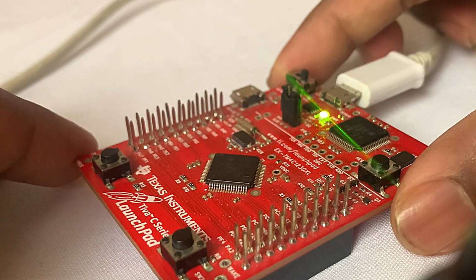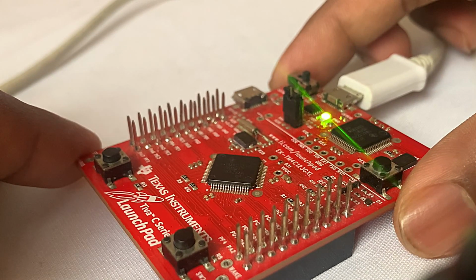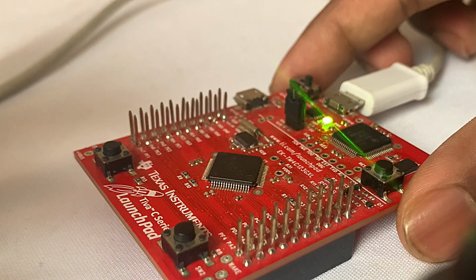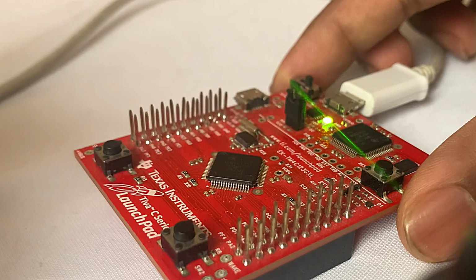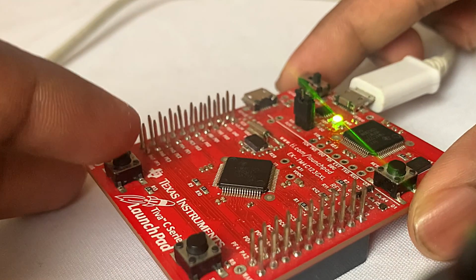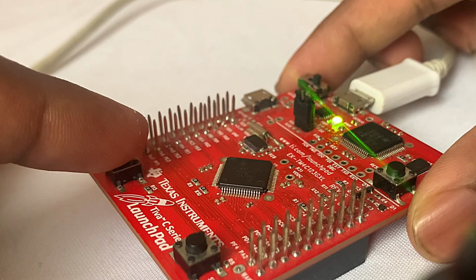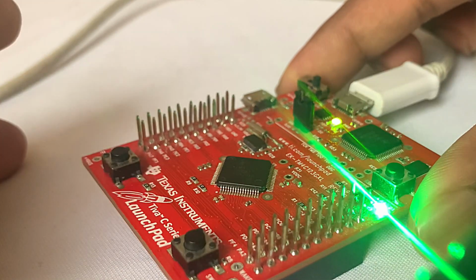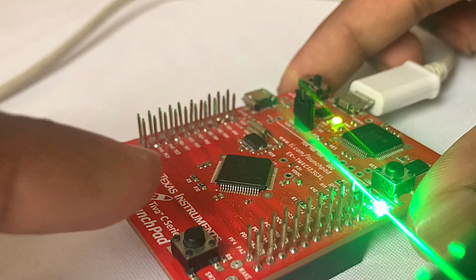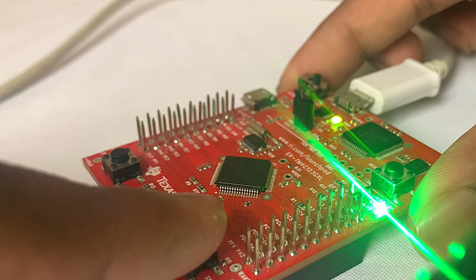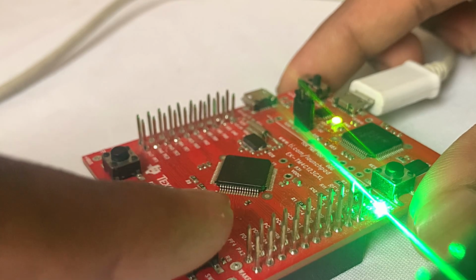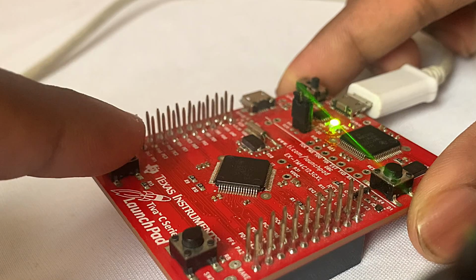Now what I am going to do is, using this program, alter or add several programming lines for transmitting some data through the UART line. Whenever I press this button which is connected to PF4, I will be transmitting the character small a in the UART transmission line. And whenever I press this button which is connected to PF0, I will be transmitting the character small b in the UART transmission line. So this will be my programming logic.